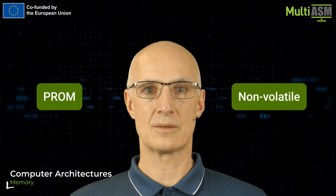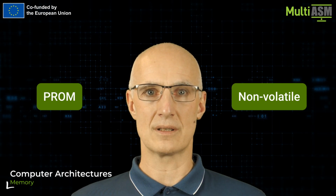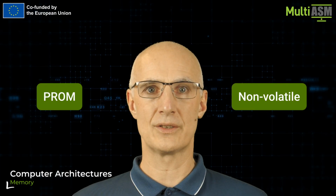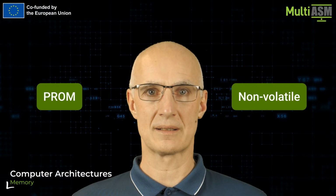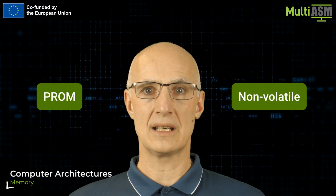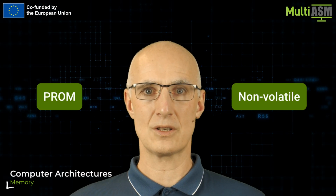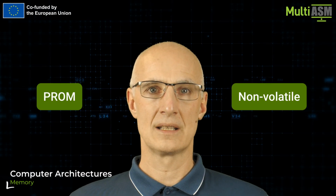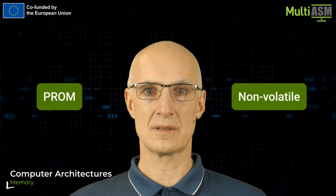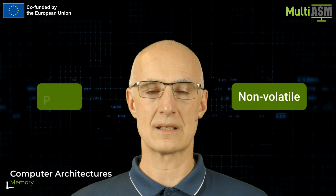PROM, programmable read-only memory, is a kind of memory that can be programmed by the user, but only once. This is why it is sometimes called OTP, one-time programming. Some microcontrollers implement such a memory, but due to the inability of software update, it is a choice for simpler devices with a short production lifetime. The one-time programming technology is used in some protection mechanisms for protecting from unauthorized software change or reconfiguration of the device.